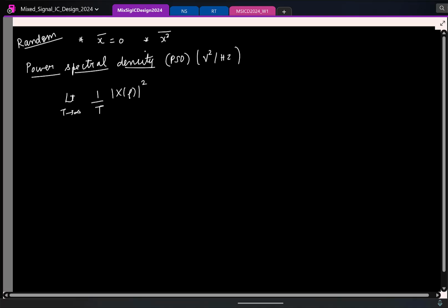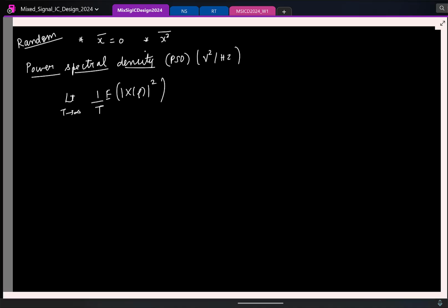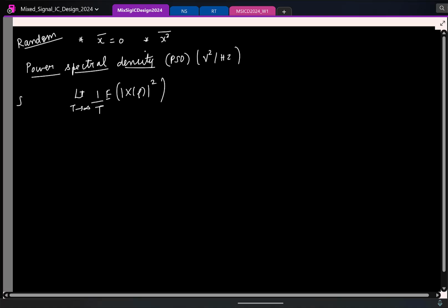One minor variation: you actually take an averaged Fourier transform. That is, you find magnitude squared Fourier transform, repeat it multiple times, take an average of it. This is how power spectral density is defined. Okay, there is nothing you can do. So I'll say Sxx of f. We'll see why averaging is important in a minute, but this is the definition.